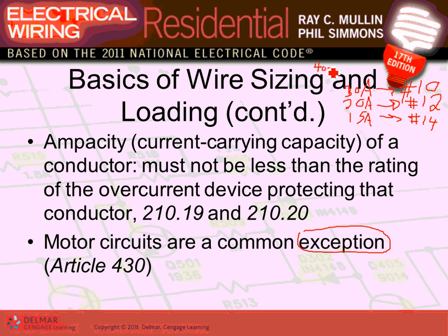And that guy goes with number 8 gauge. Between these four gauges, you have wired the whole apartment that I gave you. The whole apartment will be wired, excluding feeders and service conductor, which is just 5 feeders and 1 service conductor, with 15, 20, 30, or 40 amps. Done. That's all dwelling for you.